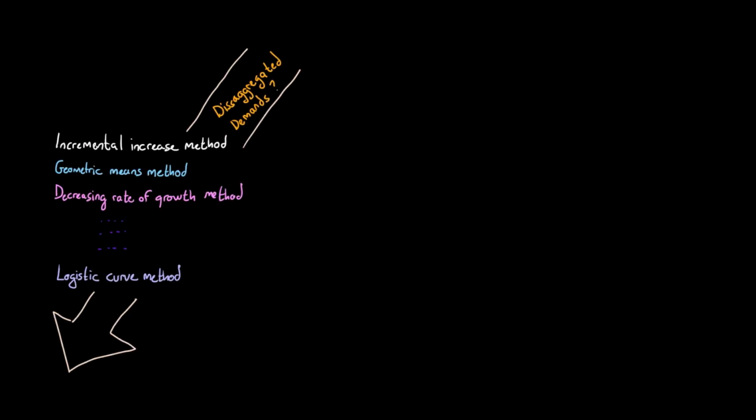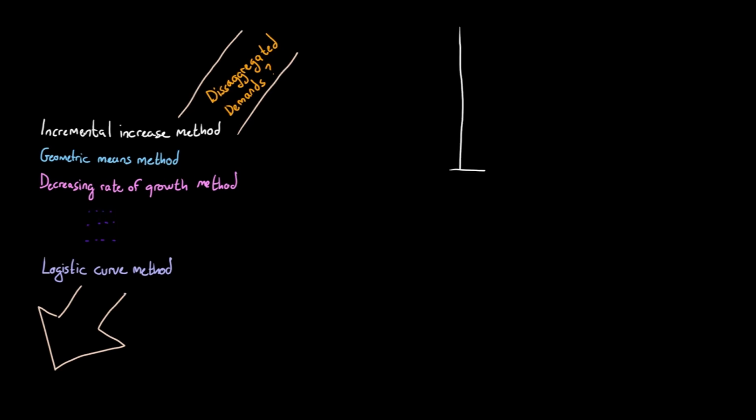There are many forecasting methods that try to account for this slowing of the growth, and there's also the possibility of disaggregating predictions for different groups, so it's easy to get lost, but let's review one that I find very practical for urban settings. The growth curve will take an S shape and tend towards a limit.